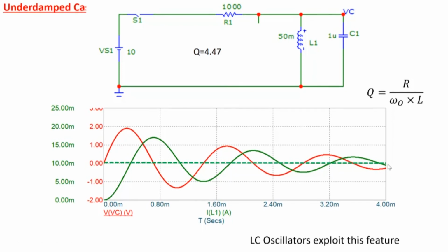Now in an oscillator, we would like the sinusoid to continue. It reaches a positive state, then reaches here, and then it should go back to the same state here. The reason it is decaying is because of the presence of R here. Note that if I make this R even larger, the oscillations will die down even slower.